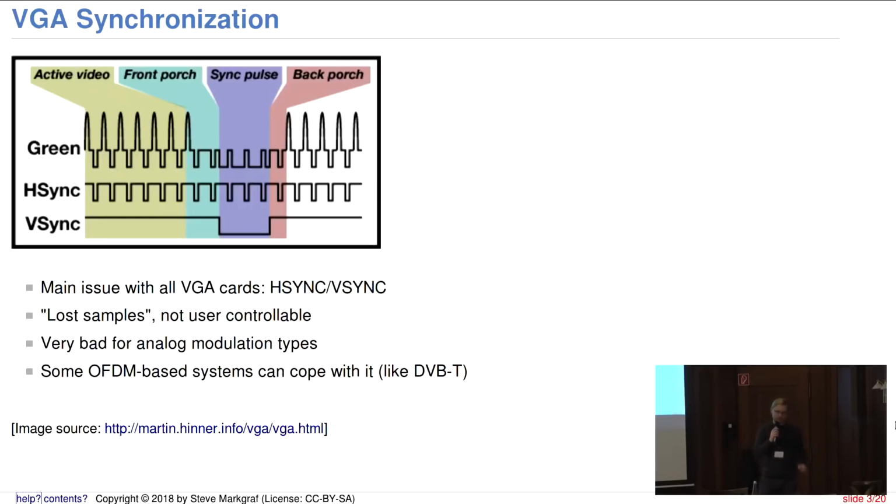But when you use a VGA DAC, you have one problem. Typically, like with analog video, there's a synchronization period and blanking being done. So there's horizontal synchronization, a small pulse, which on the old CRTs basically happened during the duration where the cathode ray is traveling back at the end of each line. And there's also a vertical synchronization period where the cathode ray would travel up from bottom right to top left again. And there the VSync and HSync signals are outputting a pulse, and the DACs are just blanked during this period, which you can see in this picture here.